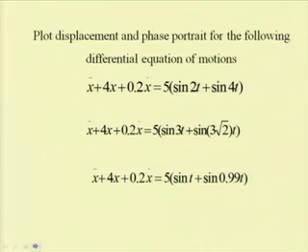Okay. So, let us see three more examples. In this case, instead of taking a single forcing function, one takes two forcing functions. So, this is a two frequency excitation case. Here one can note the equation x double dot plus 0.2 x dot plus 4 x, where this 4 is omega n square. So, omega n equal to 2. The natural frequency of the system is 2, and it is subjected to an excitation with frequencies 2 and 4 and with amplitude 5.